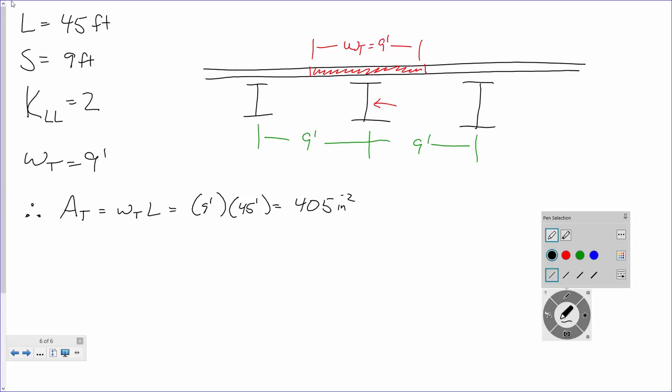Okay, so what if we had like a section? So this room, hypothetically, is perfectly square, and I have a row of desks that nobody goes under, and I know that's attributed to dead load, right? Desks are related to occupancy. That's live load. Okay. Because live load is occupancy. That's what the building is being used for. So if this is being used as a classroom, then the desks count.